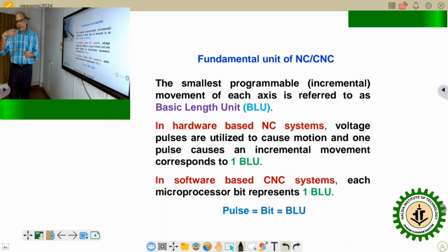That means a larger gear is connected to the lead screw and a smaller gear is connected to the motor, so that eventually the corresponding rotation of the lead screw will be rather less. So it will be alpha by Rg.